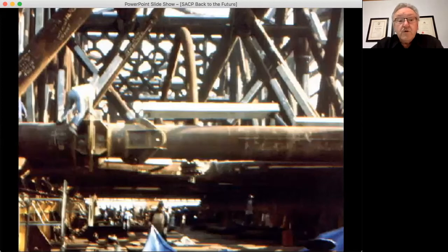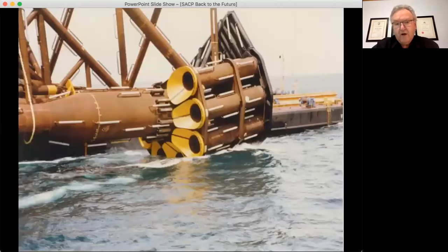So our offshore structures have vast quantities of aluminium anodes attached to them. You can see, for example, this anode here that I'm pointing to, all the bars that you can see in the photograph, each one of those is 50 to 80 kilograms of aluminium. And the FA platform that was installed off Mossel Bay in the 80s had something like 500 tons of aluminium attached to it in the form of sacrificial anodes.